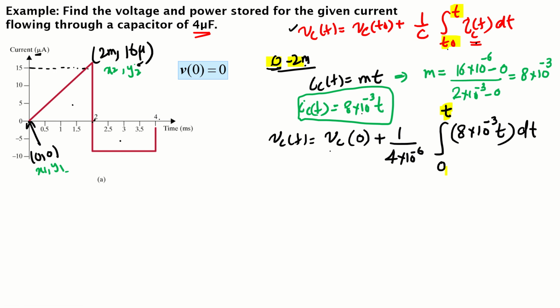So now we need the voltage value at 0. That was the initial condition. This is given in the question. Most of the time initial conditions will be given, like whether the capacitor has any stored energy, any voltage drop across it before placing it in the new circuit. For this case, this is 0.